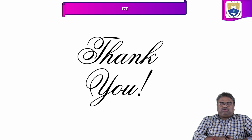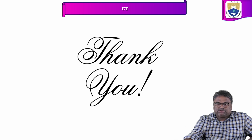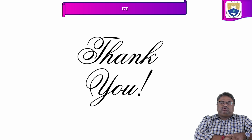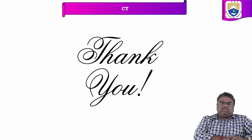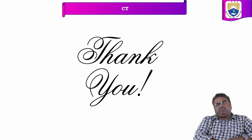Thank you very much for your attention. In this class we have discussed tests on cement: the field test and the laboratory test. The field test is how to check the cement in the field, whether it is good cement or not. In the laboratory we have six different types of tests. The first test is the fineness of cement, found by sieve analysis and by the air permeability test.